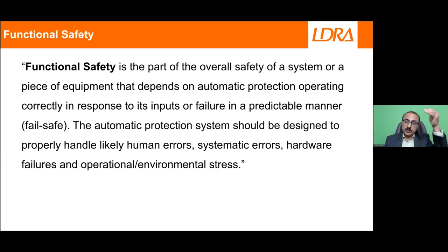Once I define, after doing a risk assessment process, which level each of the subsystems should come in, then I start my design based on that, because that includes the reliability parameters, because they should have a fail-safe operation also. In case something fails, the other channel should take over, right? Because those are the subsystems which are at the highest safety levels. And bikes, I will tell you, it is further complicated, unlike the car, because a bike is an unstable device, right? A car is sitting on 4 wheels. So we will see that part also. There is a slight definition difference when it comes to motorcycles.